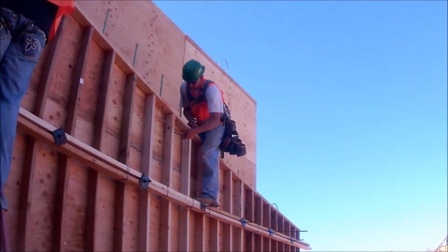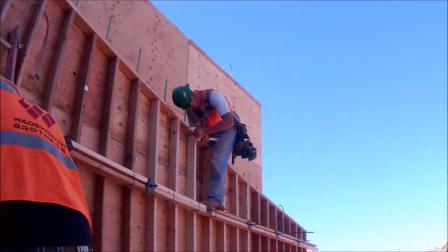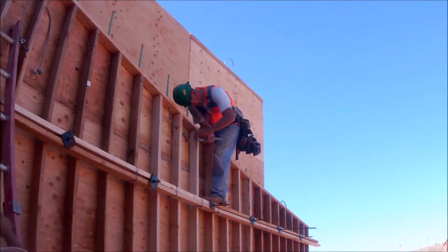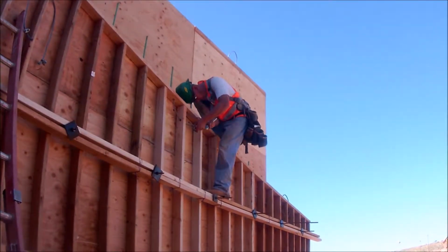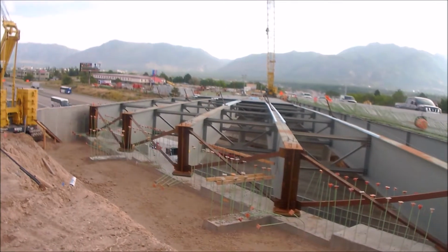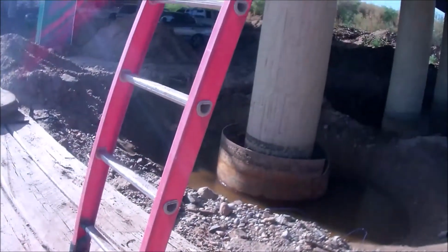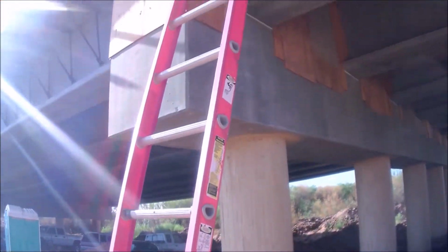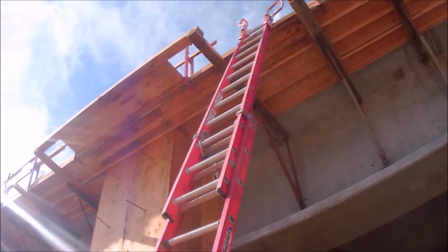Bridge construction, MSE wall construction, and other activities will require elevated work. Our main control will be our fall protection program. It consists of signage to exclude non-trained workers from hazards. Handrail installed as early as possible on structures and walls. 100% tie-off required when hazard exists over 6 feet. Workers using harnesses and lanyards must be trained. Horizontal lifelines will be installed on girders prior to placement.